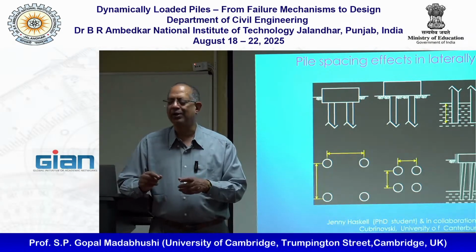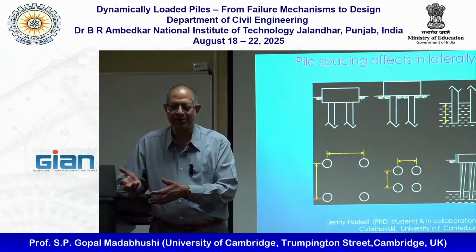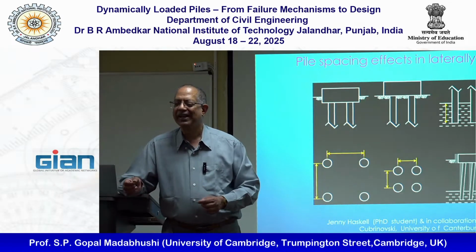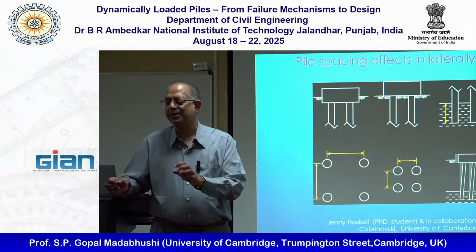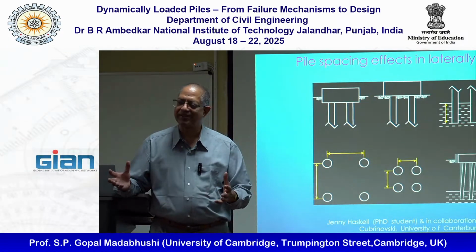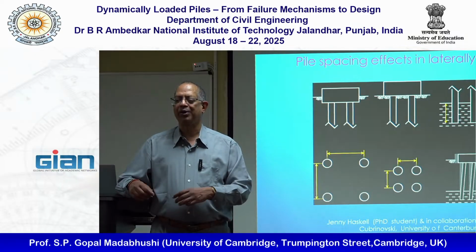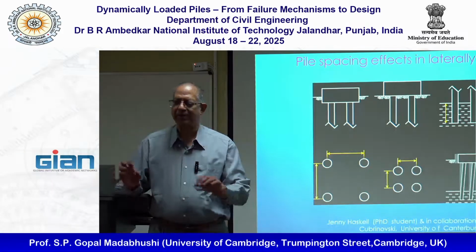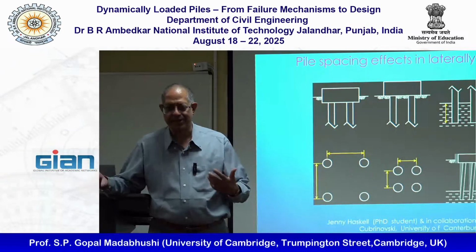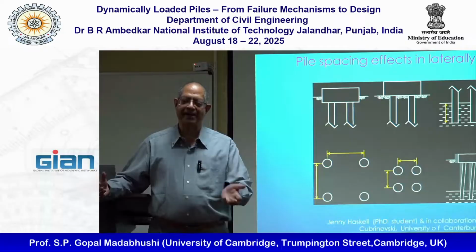This is normally called set, pile set. But the real question in soil mechanics is, is that just dissipation of pore pressure? You generate some pore pressure when you drive the pile, and if you allow enough time the pore pressure dissipates, my effective stress recovers, and therefore I can get extra capacity.